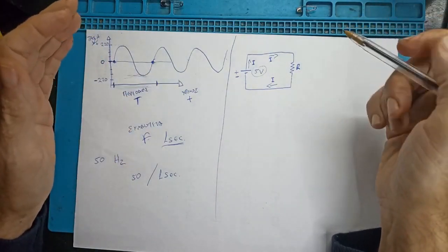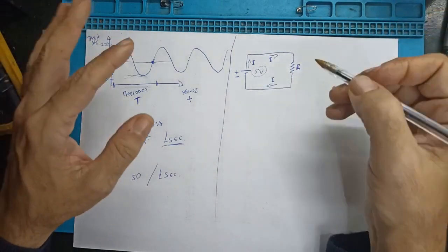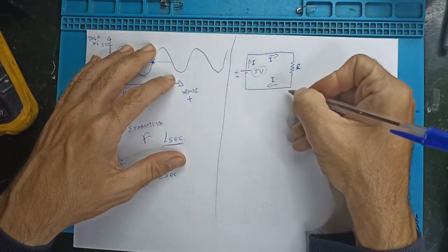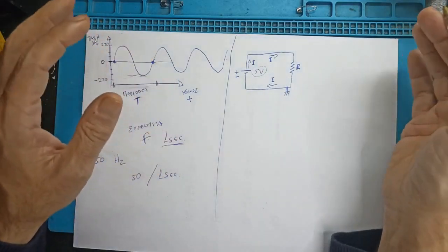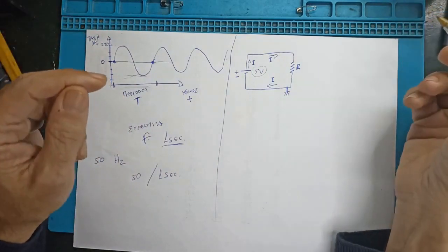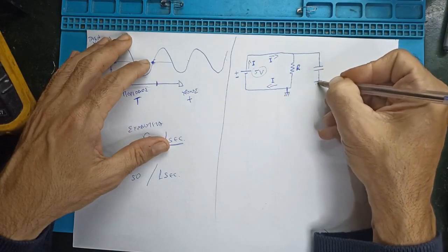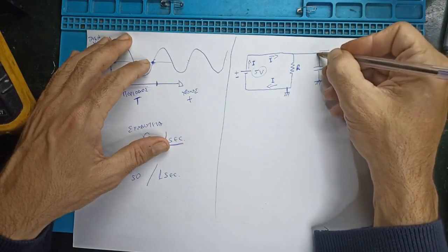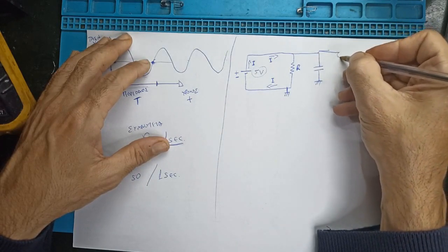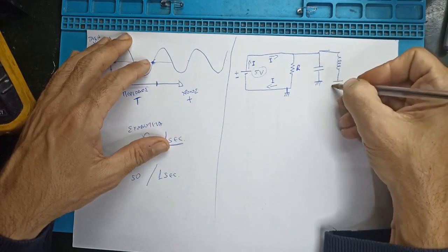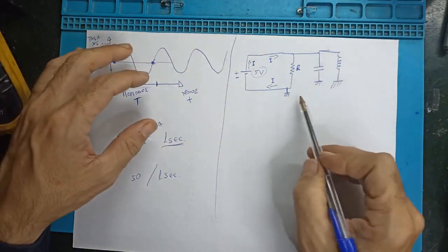Now in repairs, usually we do not measure the current. There is no need to measure. Usually we measure the volts passing through the circuits. And a characteristic when we see some designs is the grounding. In the drawing, grounding is usually present and symbolized as I do on the piece of paper. And there may be other circuits and other components, the capacitors, which will be grounded. All these ground connections imply that everything is connected together.